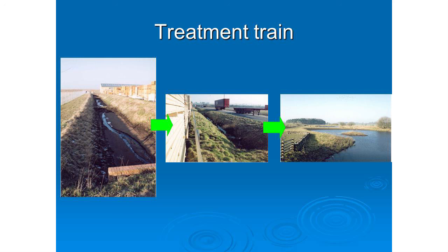And everybody looks at that first photograph, and you ask somebody about that first photograph, what's wrong with the swale? And everybody says, oh, it's failed. It hasn't. It's full of silt. It's doing what it should be doing. It's working perfectly. It needs cleaning out at that point probably, but there isn't a problem with it. And there's certainly no runoff getting further down the system, and then it runs down into the end of the system. But this next picture to me is better than any amount of testing.